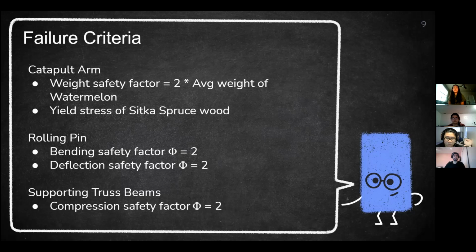We then calculated the max deflection that occurs to ensure it would not result in failure depending on our material type. For our truss structure, we again analyzed the max yield stress for the one member in tension, while the 2 slanted members required analyzing the max compression strength and buckling with a safety factor of 2.